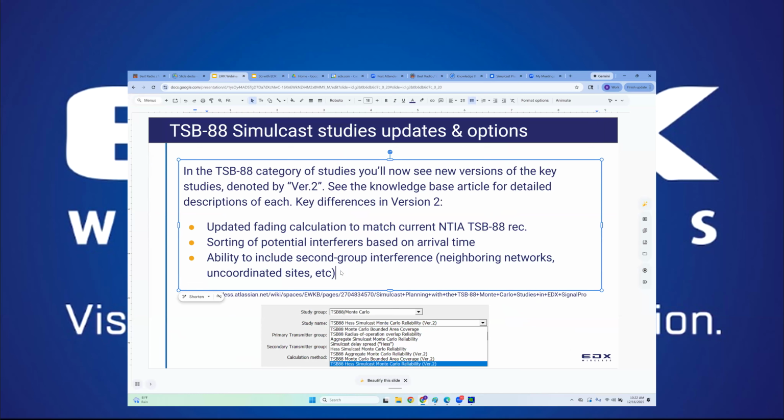We had a customer who had a mix of simulcast groups in a given network area, but also some multicast sites that were set to their own channel, especially for use cases like shooting down a beach when you might have a directional antenna and you're just filling in the shadowing along the beach. That type of site would cause a lot of potential time delay problems.